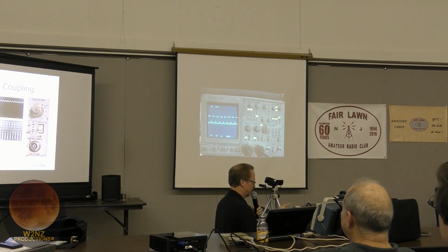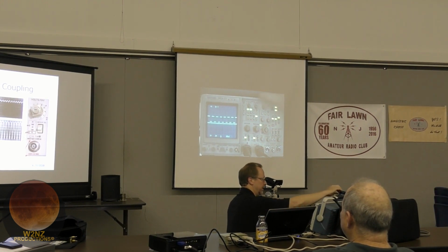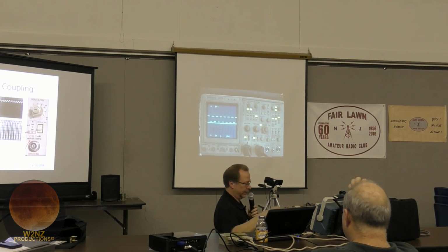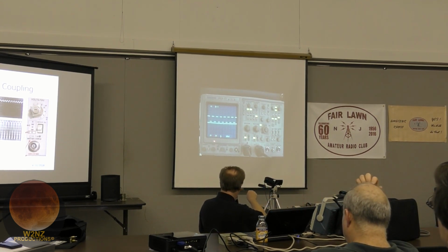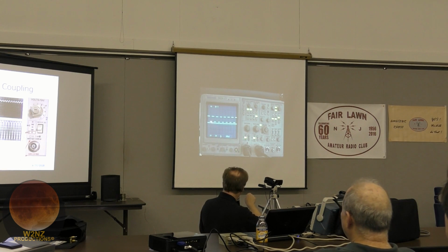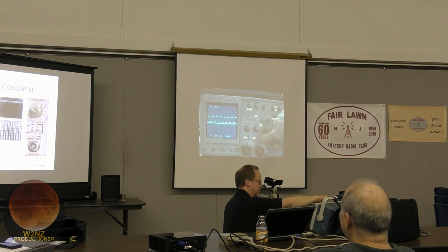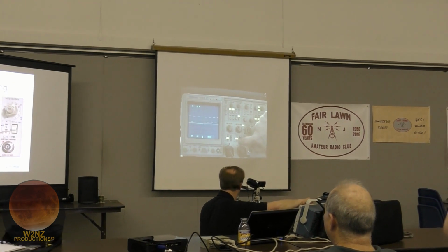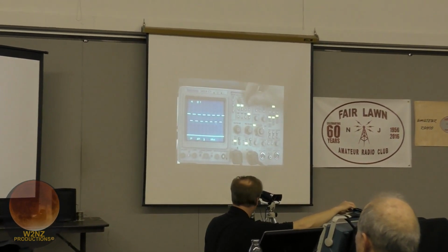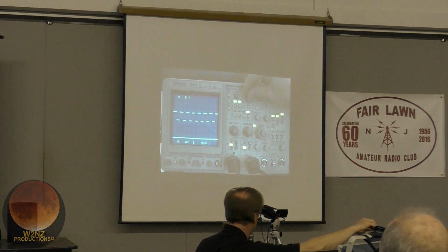I've got two signals on here. One is a square wave, and this channel right here is actually probing the power supply. If we look right here, that 2 means I've got 2 volts per division. That's on channel 2, and I've also got 2 volts per division on channel 1. You can see this signal has a little over 2 volts, about 2.5 volts of deflection on that little square wave. But if I switch channel 2 down to ground, you can see where ground is on the scope. So I can adjust the position and say there's ground.